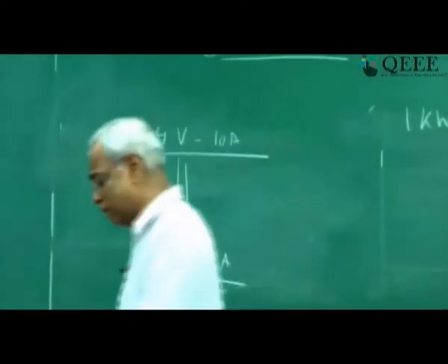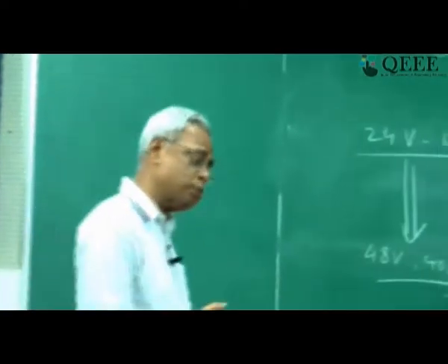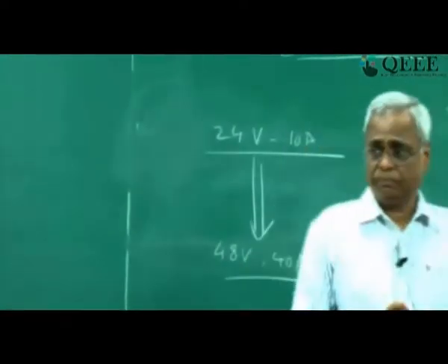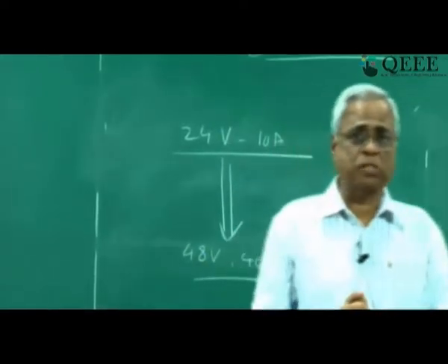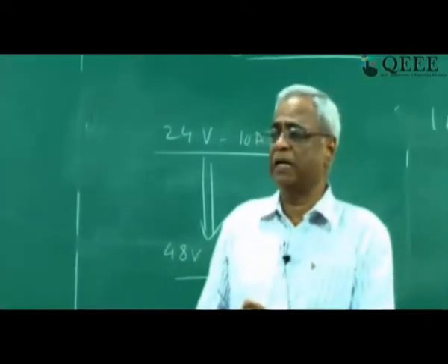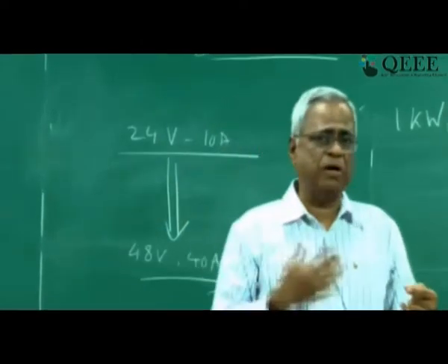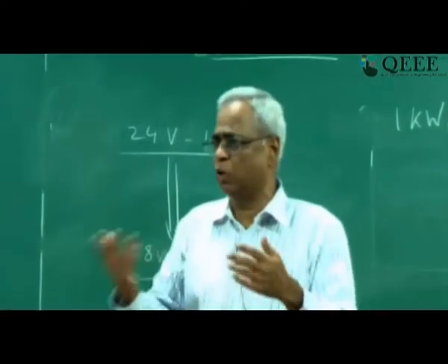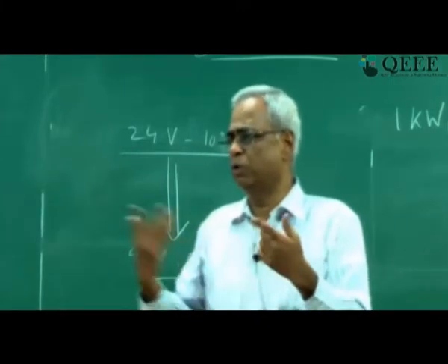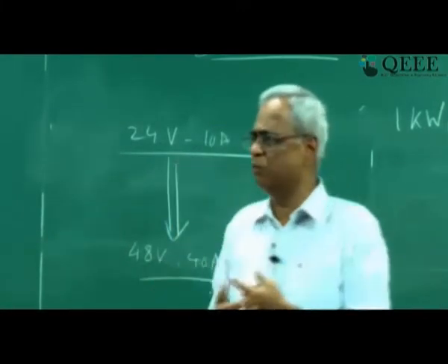Now, when you do that, then can you do it with solar DC? And then what should be the solar DC voltage? What I will propose in the next class is that we should operate at 2 voltages. One is 48 volt, another is 380 volt. So as long as the power requirement is of the order of 1 to 2 kilowatt, probably you can do it at 48 volt. 1 kilowatt you can do at 48.